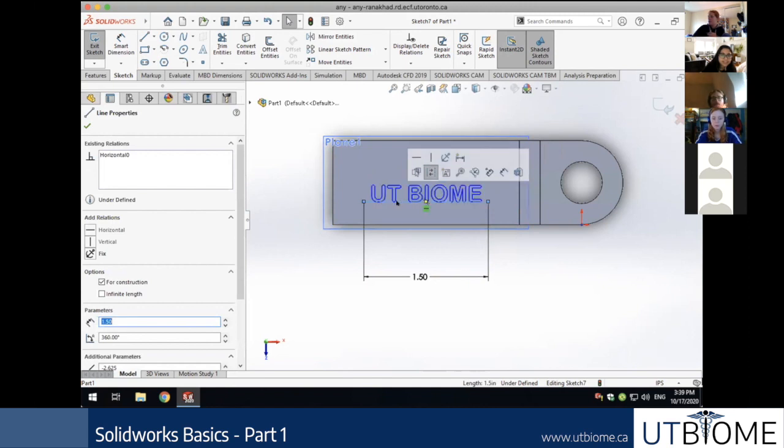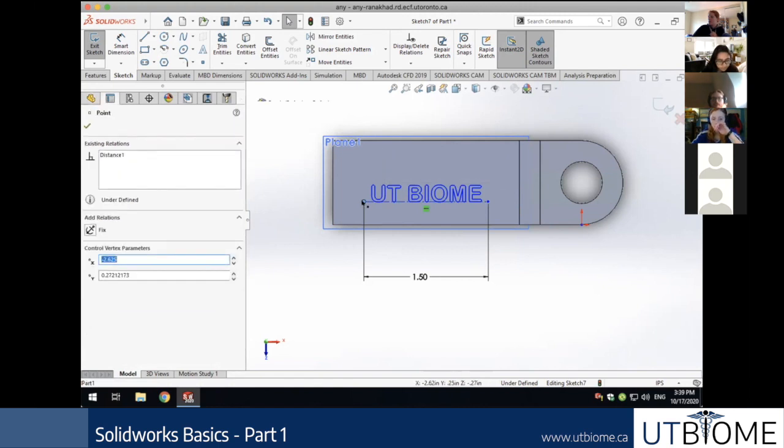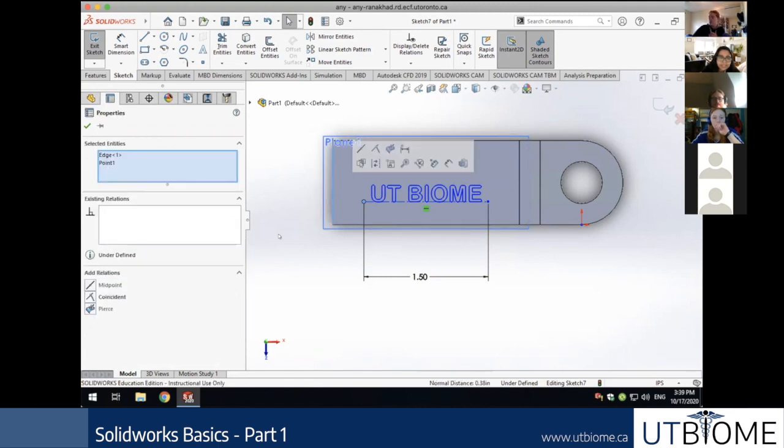Okay, so you're gonna click away or hit escape. Then click the left point of the line. Hold control. And then click the left vertical line. Yep. Okay, so now click coincident.